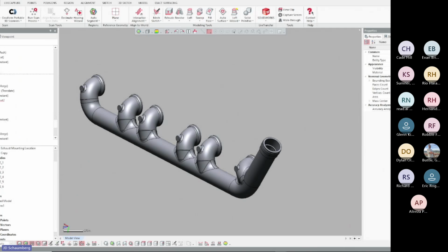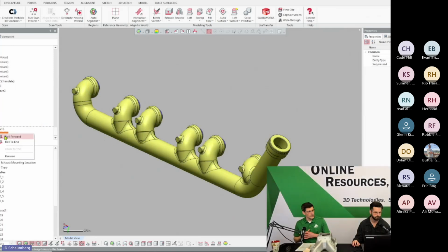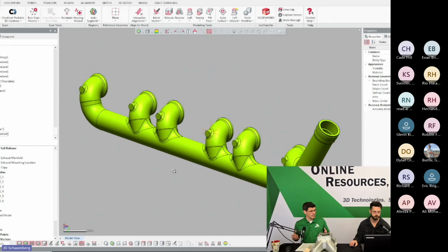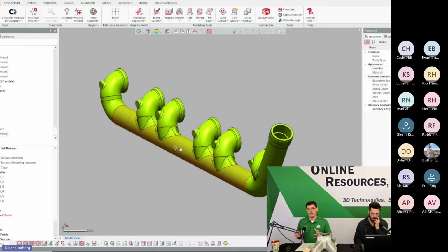So I'm just going through and adding some extrusions onto some of the pads. You'll see that over here on the outlet, I've added some machine stock to those surfaces as well. Anywhere where they're going to do a machining operation, I've added the necessary machine stock to this part and added the necessary fillets and rounds to knock off any sharp edges. So we're really looking at a full model here where the customer asks for specific stock, specific things like that. There are some other applications, like draft angles, things like that, that are really customer dependent.